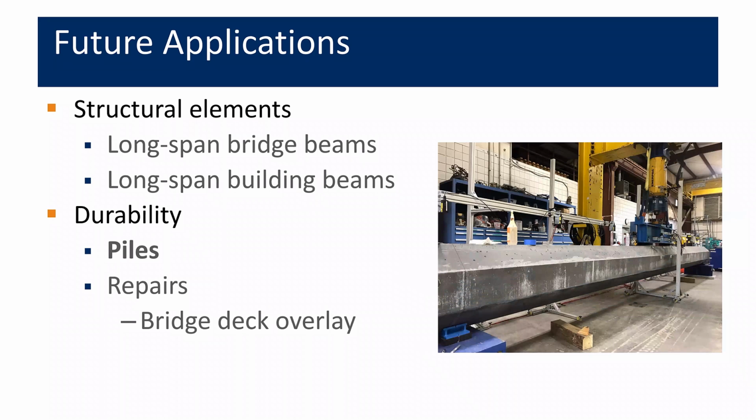We've talked about durability a bit here today, and that has applications, for example, in piles. The photo here is a picture of a pile that was cast with UHPC actually being tested at the Florida DOT Structures Testing Laboratory. And here what we're looking at is really, can we achieve through that really low chloride permeability a realistic structure even in a marine environment that's going to last 200 plus years. And I think with UHPC we're really starting to get there.